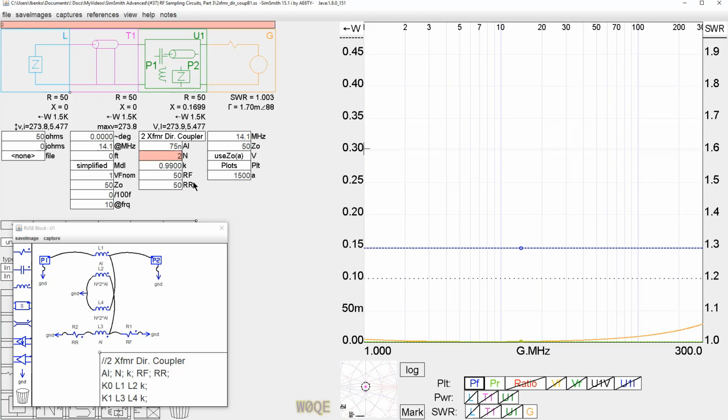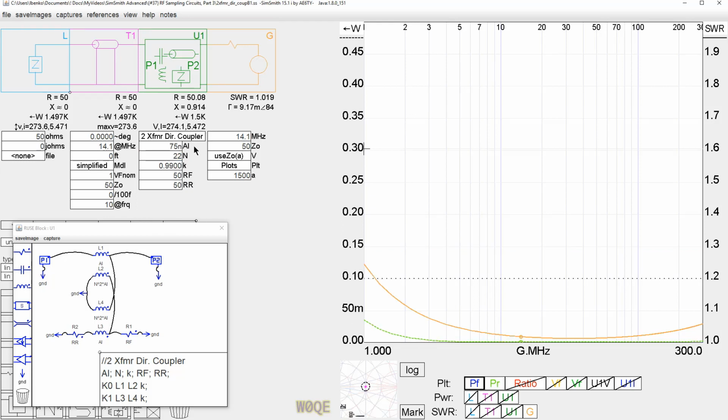But when I was trying to get this circuit to be broadbanded, I ended up having to put fewer turns in the inductor. Now, fewer turns means that the inductor saturates quicker, which means this can see less voltage here. Consequently, it handles less power. But nevertheless, this is what I built, and I measured it. And I got numbers as to what power it can handle and everything else. But we see an SWR curve like this, and this is not really that bad. I mean, it rises at 1.8 megahertz. It's somewhere in the order of 1.15 to 1.